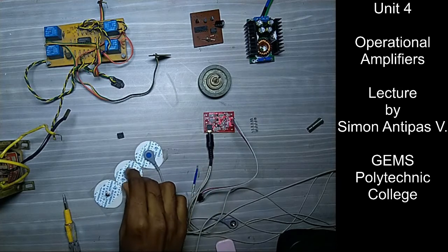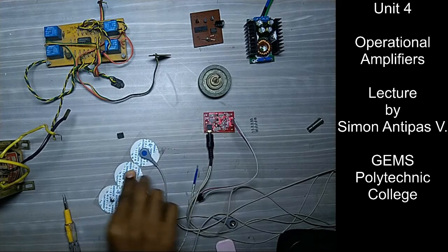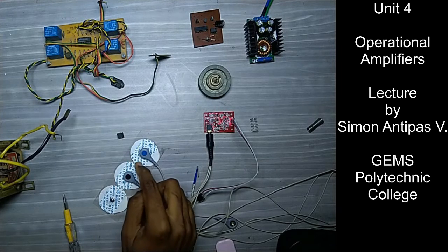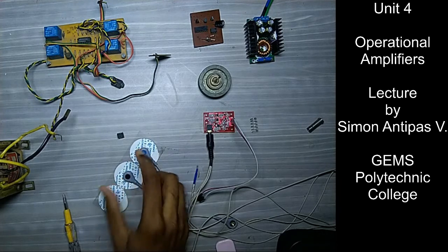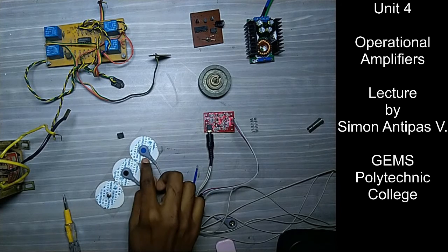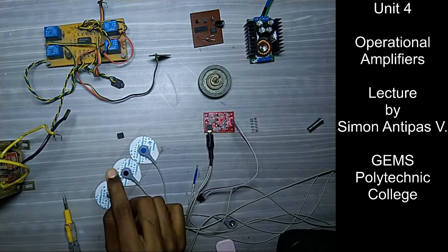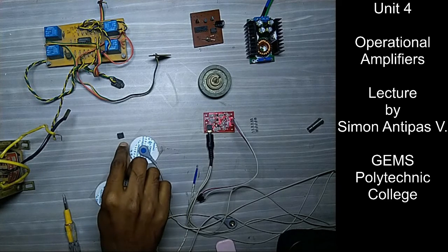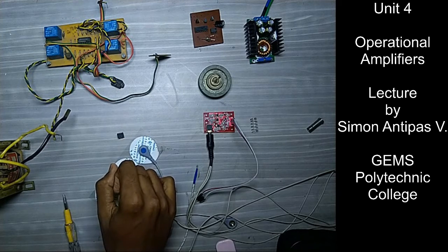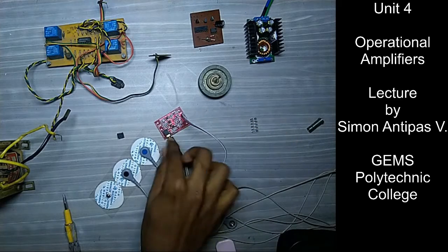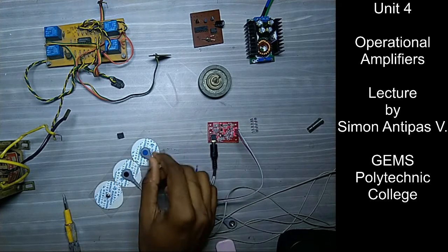For example, in this case, you have EMG electrodes that can measure your muscle activity. In other words, when you tighten your muscle, I want to measure it. Or if your heart is beating and your doctor wants to know your heart rate, they stick these electrodes onto your skin. And these are very low voltages. If I have to measure such low voltages, I need a very precise amplifier that can amplify the signals to give me a decent signal that I can connect to a recording device or a monitoring device. Those are the precision amplifiers available on such boards.